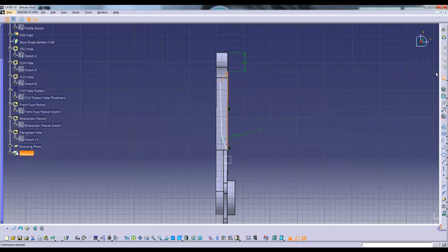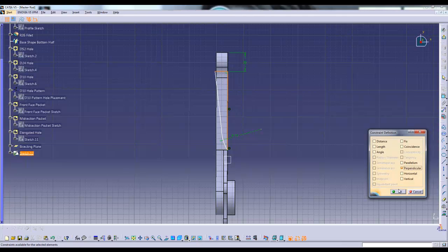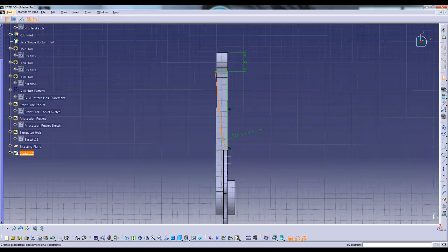Choosing to do a groove like this saves a multitude of steps and will lead to an approximate looking part. There will be a radius present. There will be an insignificant curvature looking down from the top on this part.